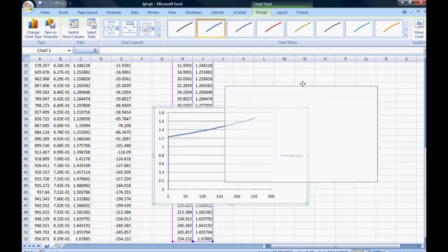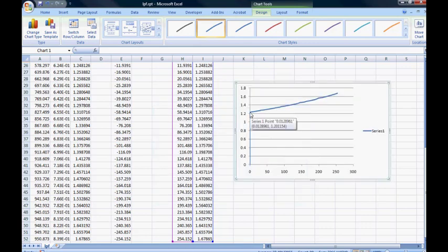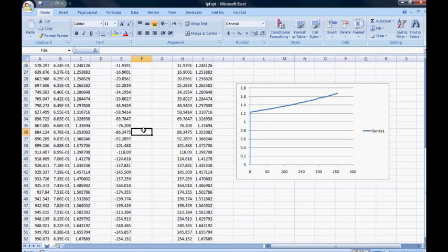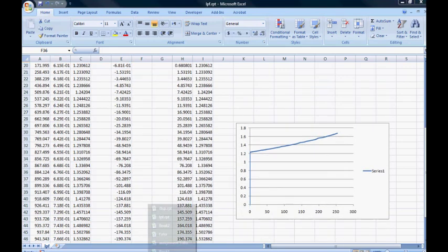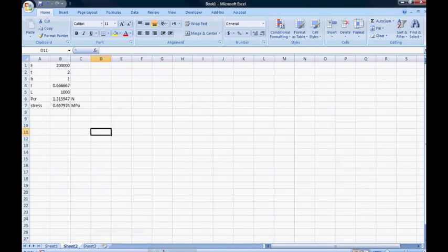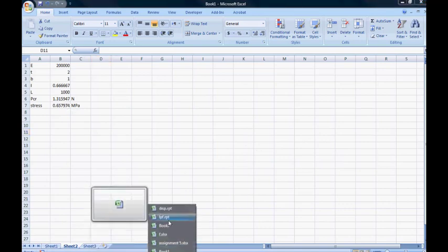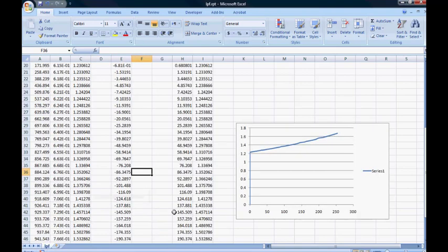You can see that at around 1.25 or a little bit higher than 1.2, the structure totally changed its direction, totally changed its path. So going back, remembering that the critical load was 1.32, so it's because of the slight imperfection, the structure buckled at a slightly lower displacement, or a slightly lower load.